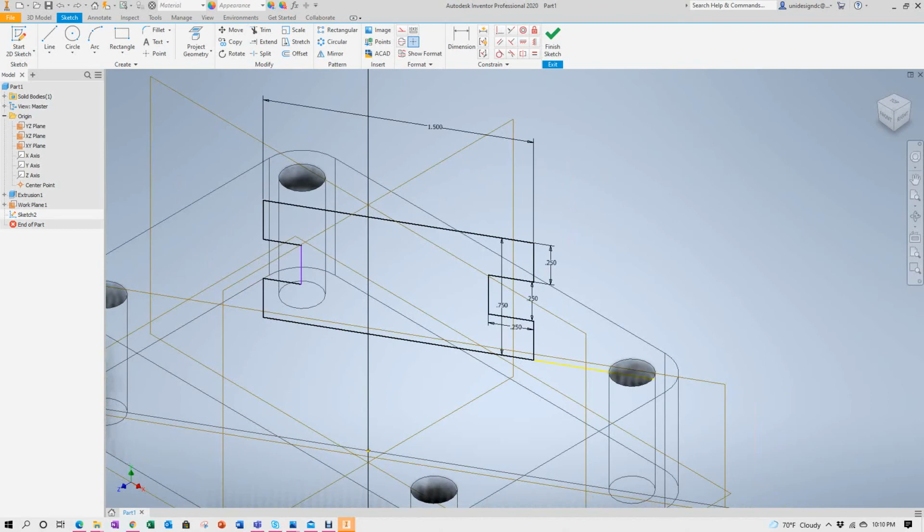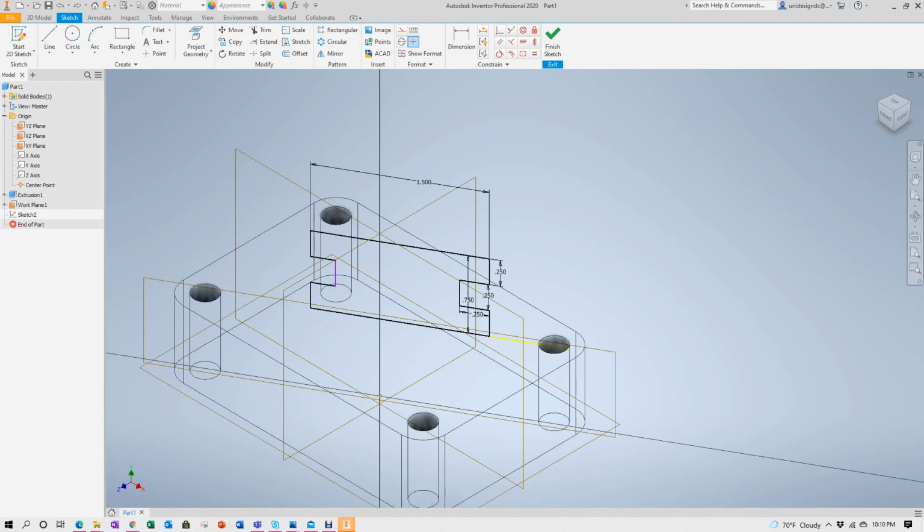So we want to create now. Let's go and finish this sketch off that we've got here. So let's create an arc, a center point arc. So what we want to do here now is go to our arc command. Let's go center point. I want to go from here to here. Actually, I don't want to use that one. I want to go tangent here. So let's go to tangent arc. So let's go select this one and this edge.